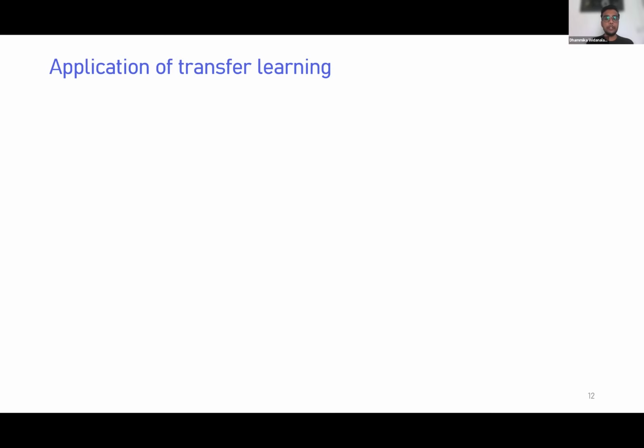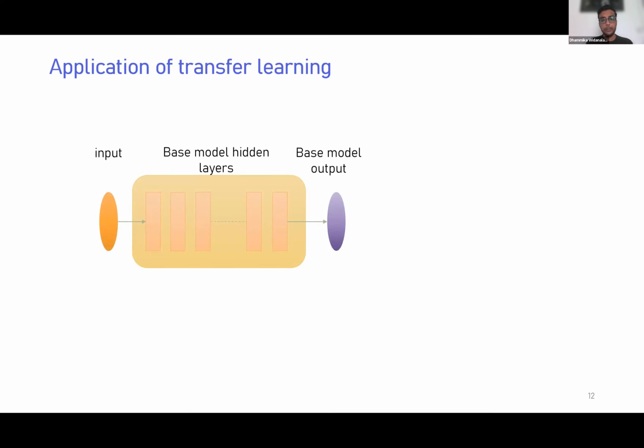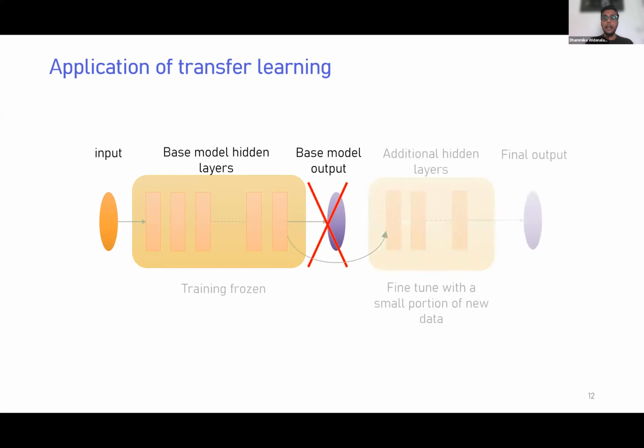To address that problem, we looked at transfer learning. In a nutshell, you have a neural network and you train it on a certain condition, which we call the base model. So we might train this with certain temperatures, as you'll see later on. Then you transfer some of this knowledge across, because the characteristics are very similar on the new task, on the new operating conditions. But when you're transferring, you need to remove some of the layers. You retain most of these layers, and that's the transfer learning aspect. You have to retrain the new layers that you might introduce and the new output. In this case, we were using current and temperature as our inputs and the capacity as the output measure.